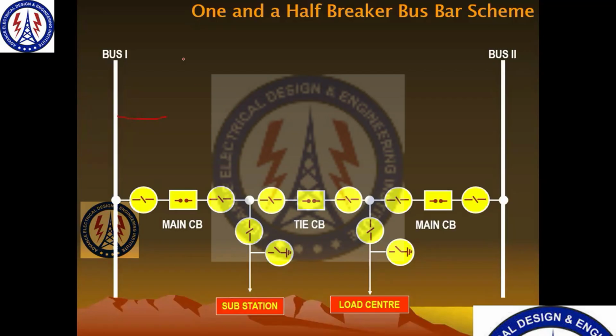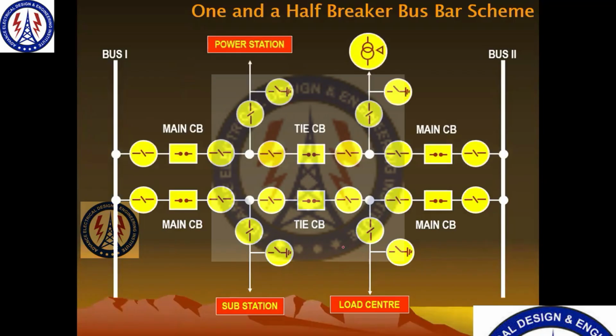In your substation, only 9 bays. So 9 bays means only 4 dia with 2 bays complete and 1 dia with 1 bay only. So this is how the half dia will be in the system. Then this is the other dia. So how many feeders do we have? 4 feeders.